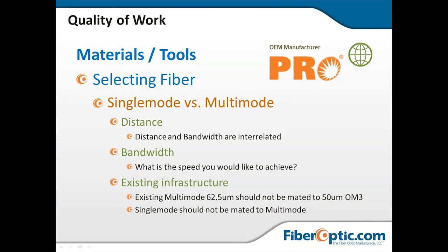So the signal, as it propagates down the complete fiber length, at the other end is just receiving constant light on. It doesn't see the Morse code that typically makes up a fiber optic signal: on, off, on, off. It's not seeing the flashing. It's literally just seeing a dim, steady light, and therefore it doesn't know how to interpret that. So those are two variables you need to take into consideration. The other thing is, what is your existing infrastructure?